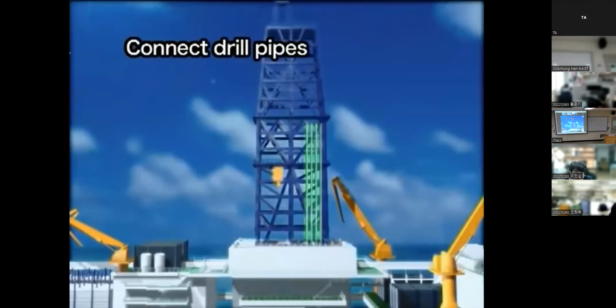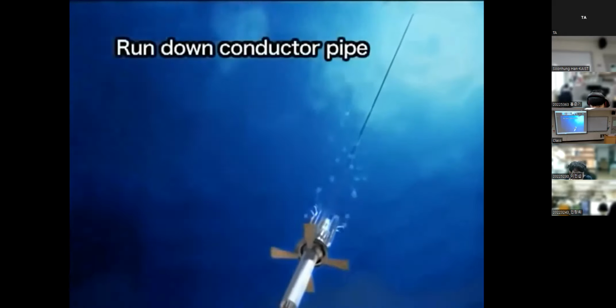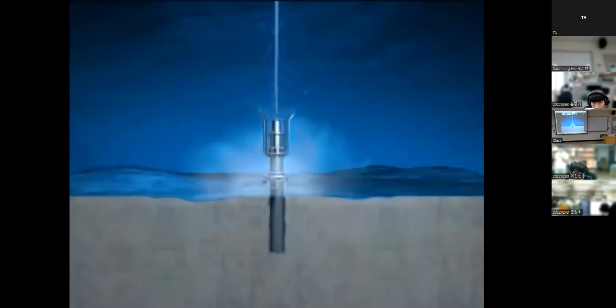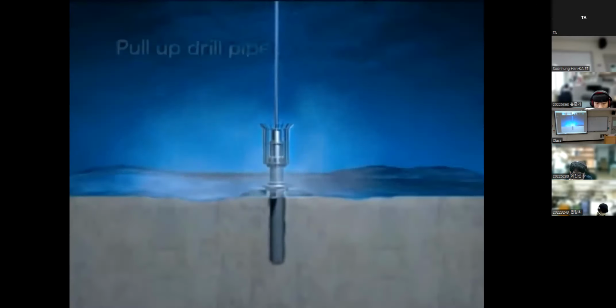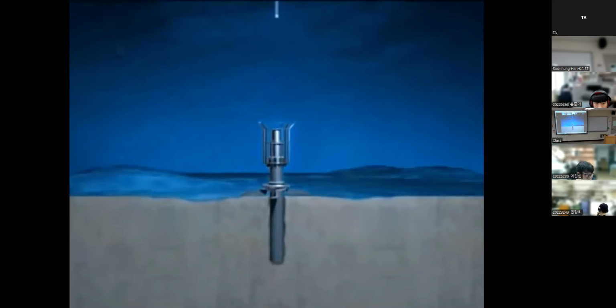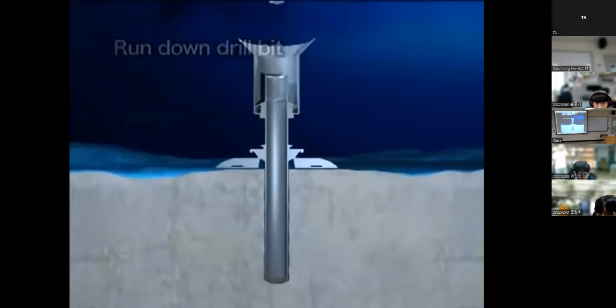First, the conductor pipe is installed. As the drill pipes are connected, the conductor pipe and guide are run down to the seafloor. After the conductor pipe penetrates the seafloor, the drill pipe is released and pulled back to the vessel. A large drill bit connected to the bottom of the drill pipe is run down to the seafloor.